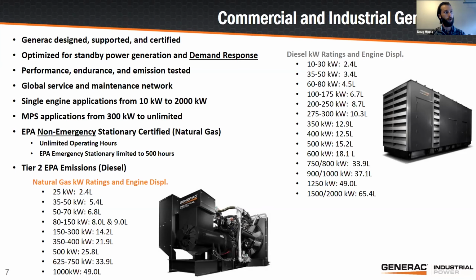If you have a lot of variability in your power needs, a wide fluctuation in your power requirements, for part of the year during growing or harvest season, let's say you regularly are using 500 kW, but during a different time in the year, you're only using maybe 100 kW. We can parallel two smaller generators together to more appropriately balance that fluctuation in load.